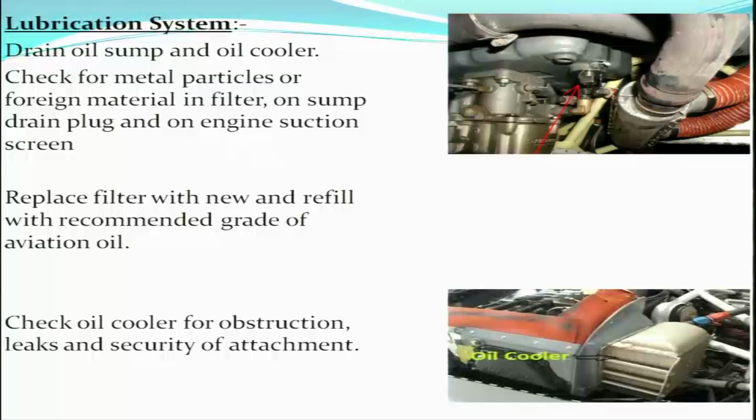Then comes your lubrication system. Drain the oil sump and oil cooler. In most of the piston engine aircraft, the engine manufacturer calls for replacement of the engine oil at every 50 hours of operation or 4 calendar months, whichever is earlier. So as part of the 50 hours schedule, in case your aircraft has flown 50 hours, we need to replace the engine oil.